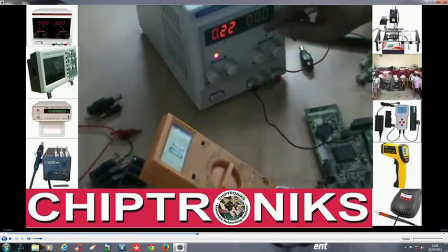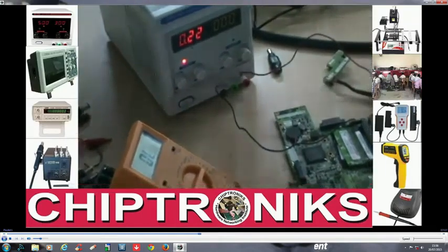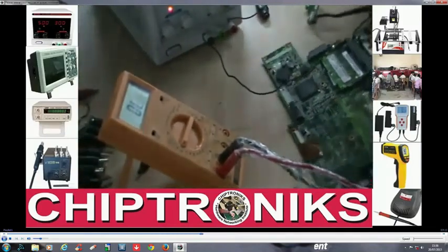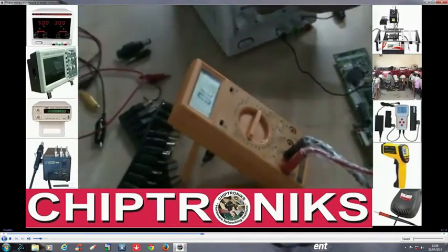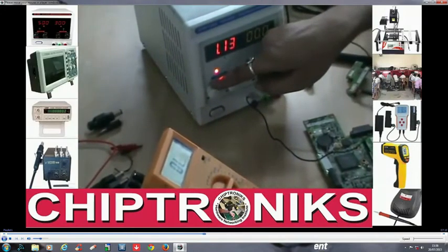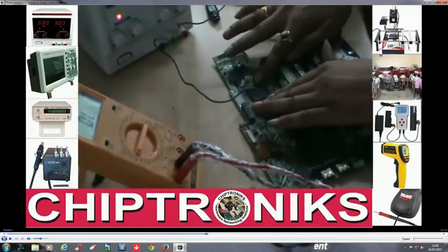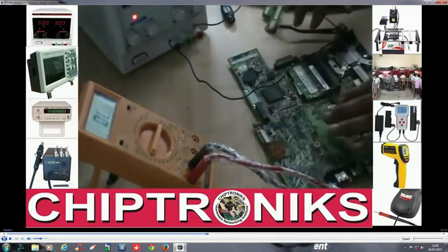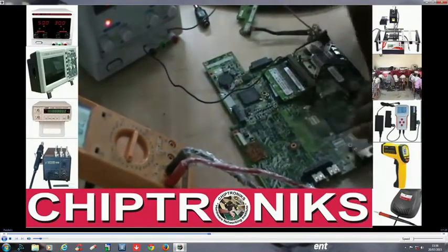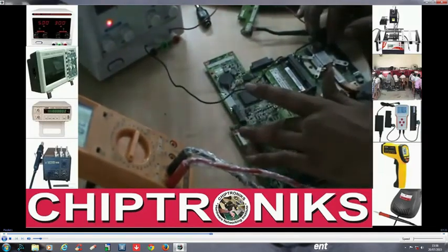Status is red LED, it means motherboard short, but we need to know where is the actual component fault. Now here what we do, increase ampere slowly, and then we check heat. Which component is going to heat? Like MOSFETs, you check everywhere like this.